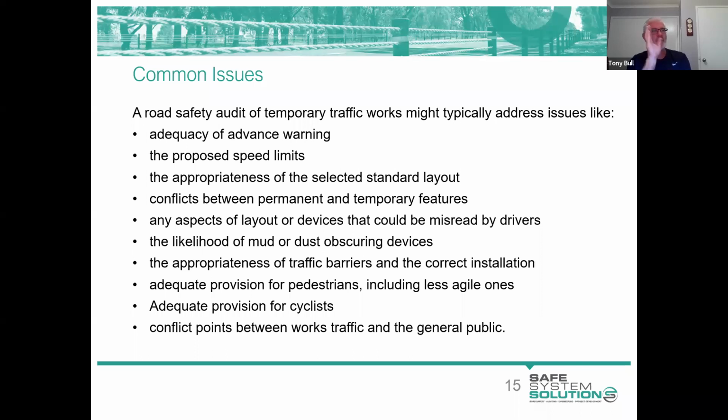The appropriateness of our traffic barriers. This one's really important, that you ask the questions. Have these barriers been installed to the manufacturer's specification? And even ask that they can prove that, because too many barriers are just butted up together without the correct connectivity in place.